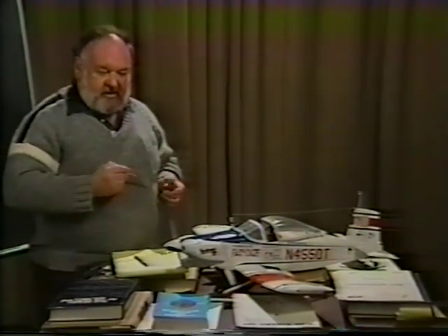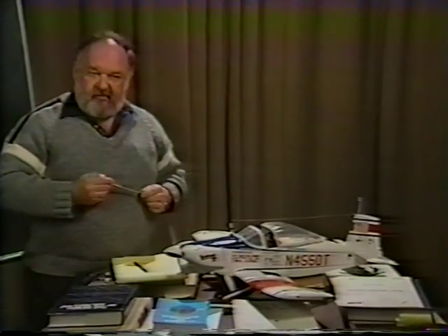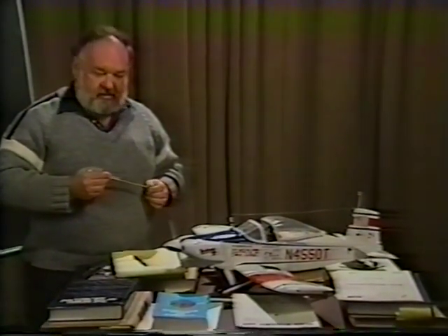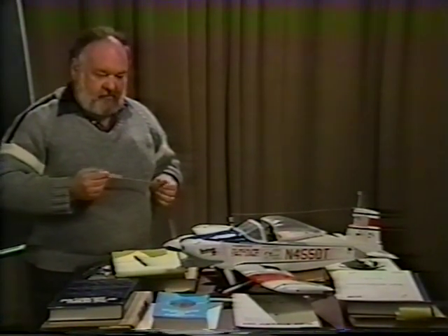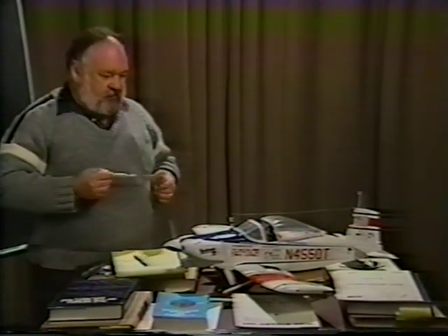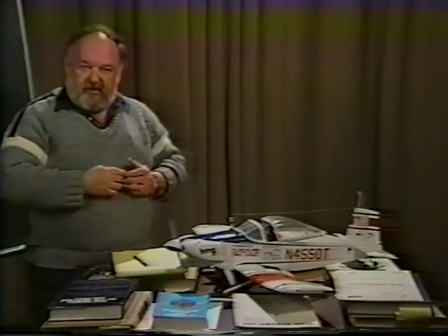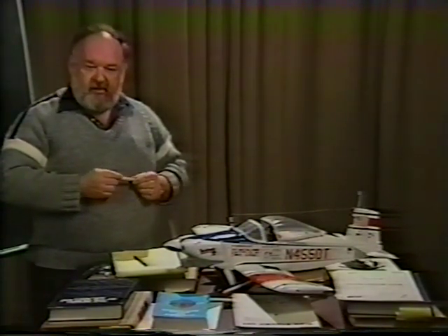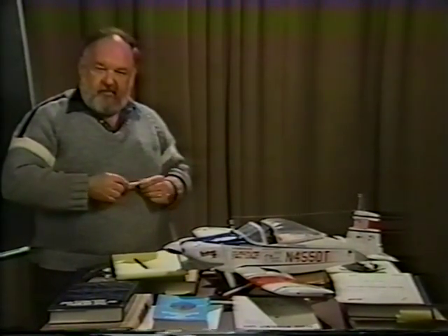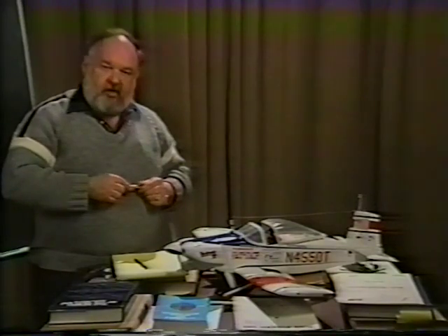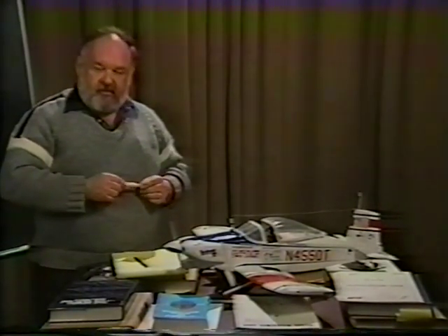I'm not sure really on the T-18 whether he has any twist in the wing. He may have 1 or 2 degrees of washout on it that would assist in giving the proper stall pattern all the way around. But it does represent a typical homebuilt, and it does represent a good design, and one again where you do have to compromise. What you'd like to get in one aspect of the design may be structurally or cost-wise more difficult to make, so you balance that out with the overall design of the airplane.